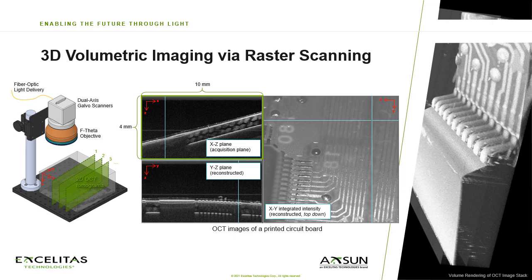There are various methods for beam scanning in OCT, but a common one shown here is based on a dual-axis galvo scanner and objective lens that create a flying spot or raster pattern in the XY dimensions, while the spectral analysis of the interference signal is generating the Z dimension. Other common scan geometries are helical or cylindrical in nature, such as when scanned by a rotating fiber optic inside a borescope. Ultimately, the 3D dataset can be represented as a point cloud, a series of cut planes, or reconstructed into a top-down view or volumetric rendering as shown here.